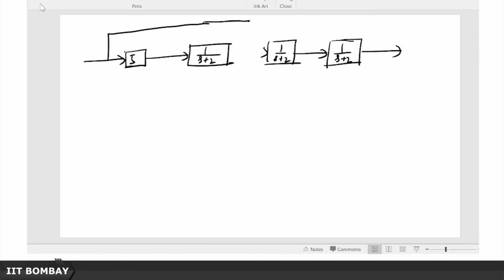and let me remove this here and add a summer here, again the sign of the summer. So I need a 7 because that was what the gain was. Now you notice that I have that same input channel, this u. So what is happening? 5 times u is passing through all 3 blocks, right. 7 times u is passing through only 2 of those blocks. Now you can easily guess what I am going to do next.